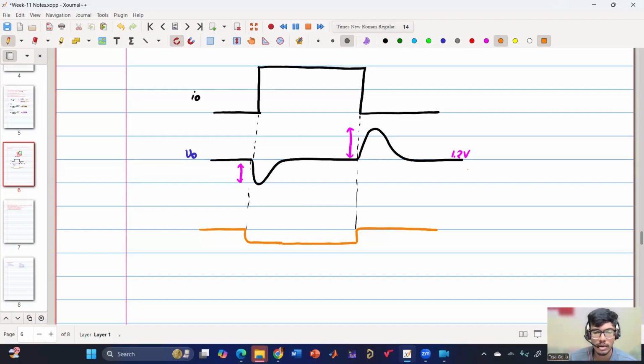But what is happening? I am now making sure that V0 settles faster. So now this voltage can be at 1.2 volt. This can be, say, 20 millivolt lesser, 0.02. So now it is coming at around 1.18 volt. So whenever there is high application requirement or high load current requirement, then I'm reducing the voltage of the processor so that I can reach the new steady state faster.